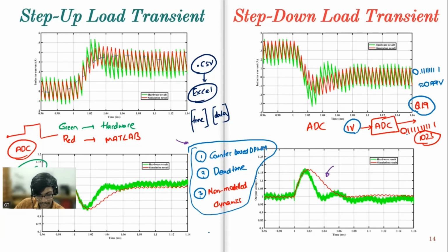And again, when we say DAC, it is converting a digital equivalent number to analog voltage. Say again, it is Q1.11 format with offset binary. Say I want the output voltage to be 1. In 2's complement, the sign MSB will be 0 for positive voltages, and in offset binary it will be 1. So 1 bit and then 11 bits.